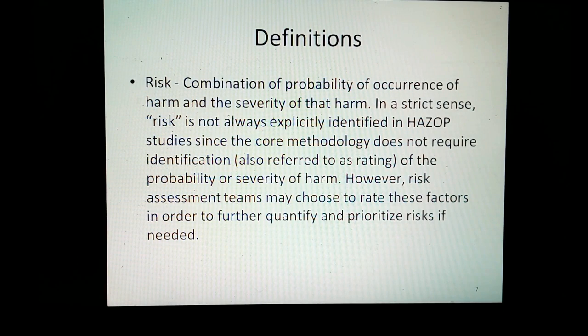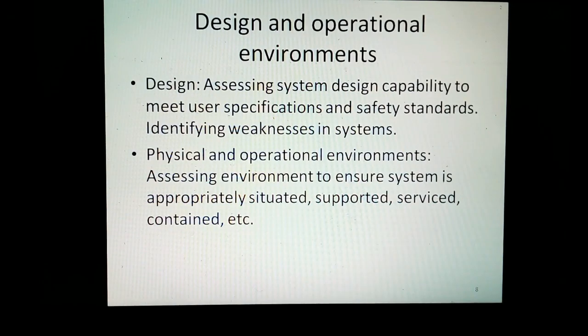Uses. HAZOP is best suited for assessing hazards in facilities, equipment, and processes and is capable of assessing systems from multiple perspectives. Design. Assessing system design capability to meet user specifications and safety standards. Identifying weaknesses in systems, physical and operational environments. Assessing environment to ensure system is appropriately situated, supported, serviced, contained, etc.